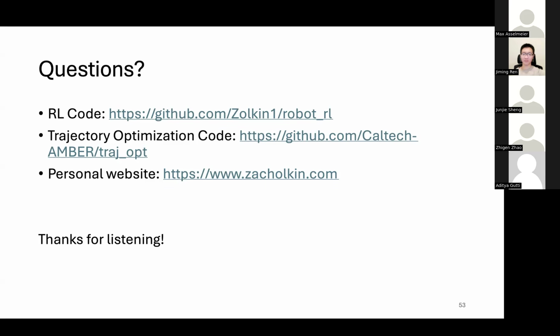That's a great question, and I think it's really hard to answer. With the baseline policy, we had classic terms: a phase reward, a height reward for the base, a velocity tracking reward, and a few regularization rewards. I can't say exactly why. The only difference was in the reward; you're right, we used the same domain randomization.